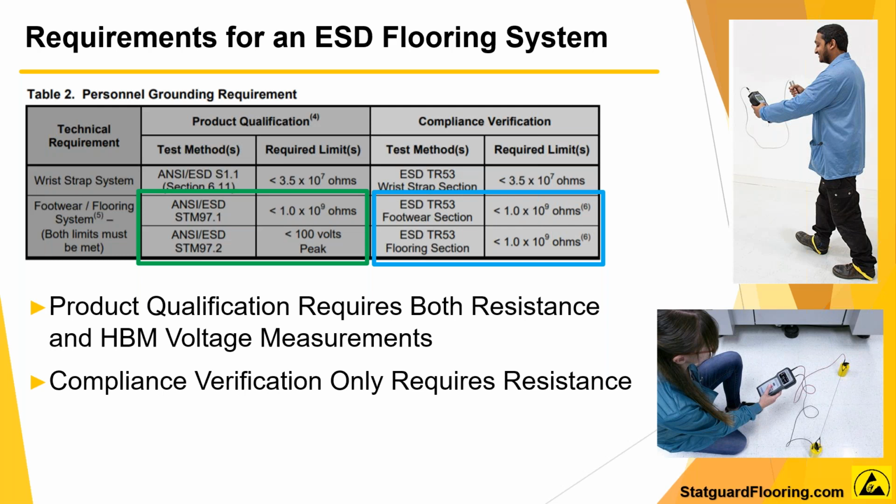Pictured on the top right is an operator using a body voltage verification meter. This meter measures the HBV, which is the human body voltage, on a person in combination with ESD footwear and flooring materials, both pre and post installation, according to IEC 61340-4-5 and the ANSI ESD STM 97.2. Pictured bottom right is an operator performing periodic test procedures based on the ANSI